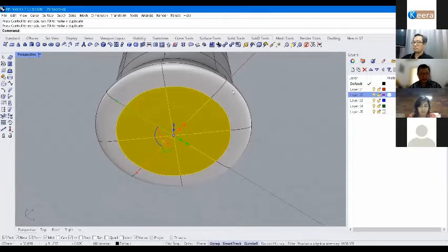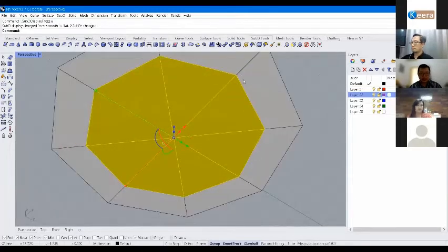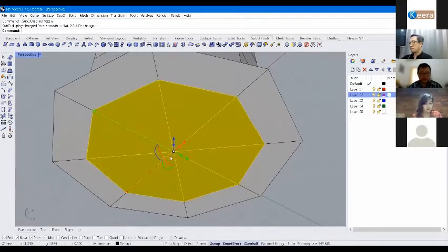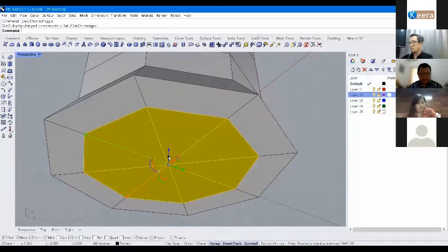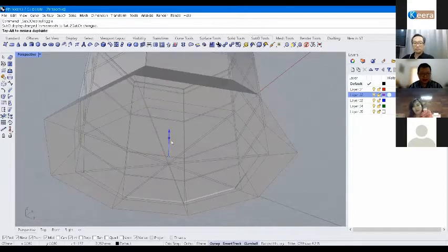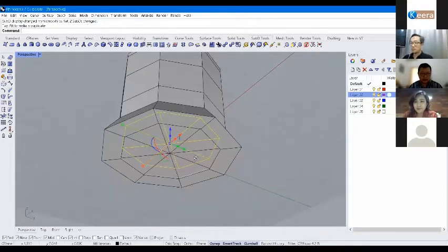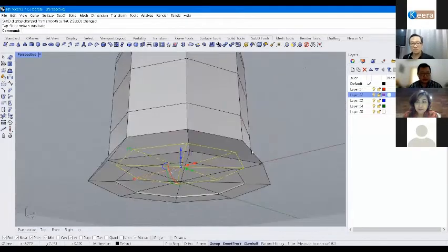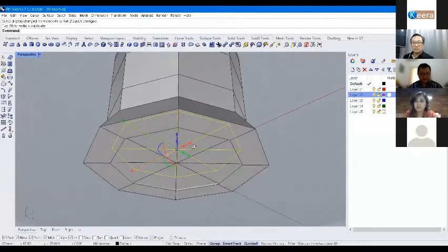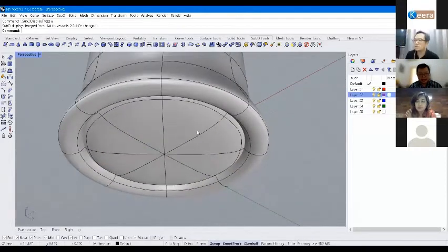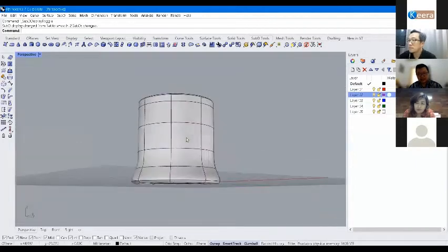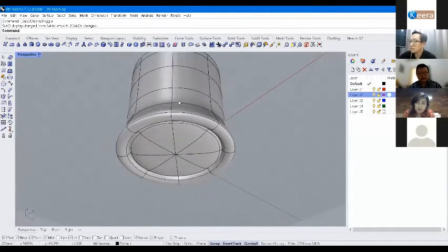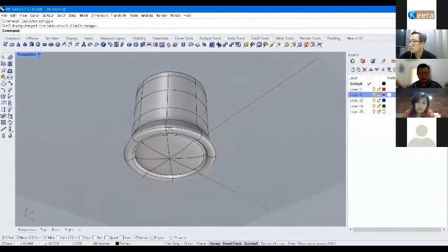If I press Tab, see, this makes a new face here, and then I can do a direct extrude as well. You can see the gumball here, and a button, and then I can drag it, so it will make an extrude of it. I will show the Tab. See, like this. That, for me, is the most powerful thing in sub-D.